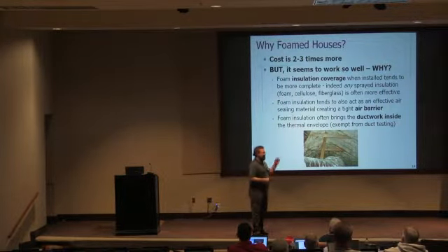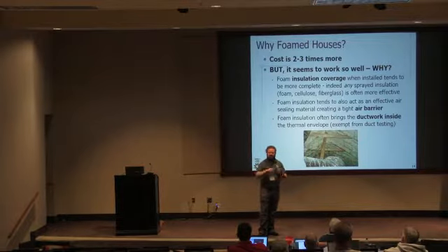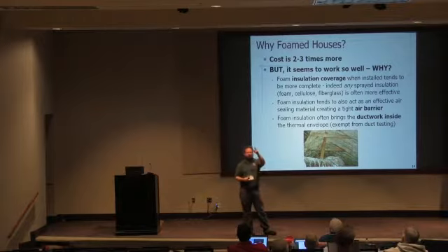I've seen pictures where they sprayed the foam and either the mix was bad or the surface it was applied to was too cold, and basically the foam didn't bind well. It shrinks up, and they drywalled it up. You come in and hit it with an infrared camera, and you can see that even though it's a spray foam wall, it's got tons of heat bypass through it because they did a bad job with the installation. What's the fix for that?